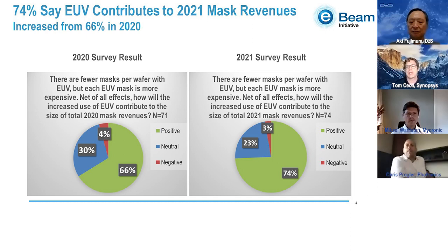And then potentially, as these new multi-beam mask writers come out, which are more capable, there's some opportunity to do hybrid masks where part of the mask may be curvilinear and some part may be rectilinear. For a multi-beam writer, that will cost the same because they don't really care which part is curvilinear or not.